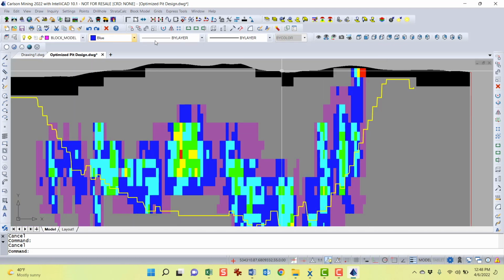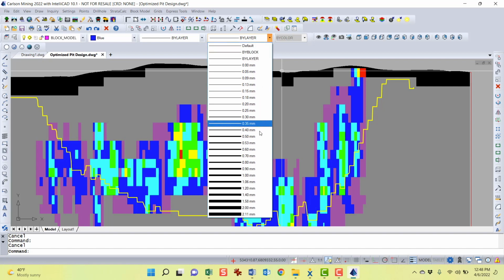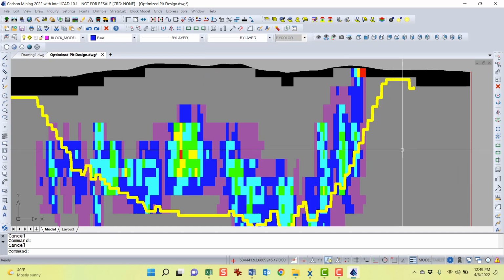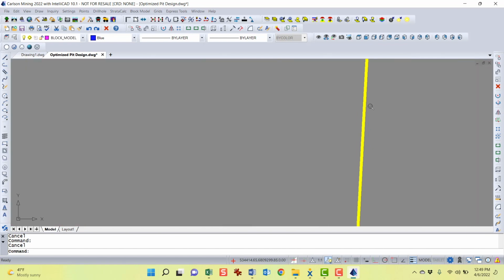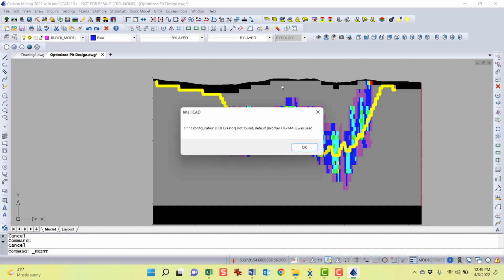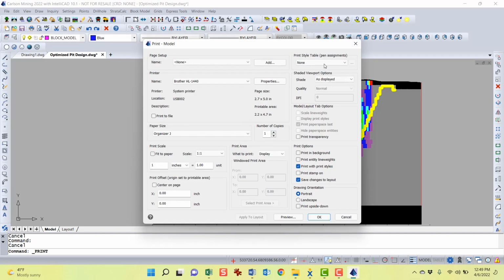And that's part of the properties of a polyline. You can give it a line weight here in millimeters. You just pick on something, highlight it, change its weight. Maybe I'll make it thicker yet. As I zoom in, it stays the same. It doesn't change. And that can be plotted too. So if you go to File and Plot, there's an option for plotting line weights somewhere. I guess scale line weights there.